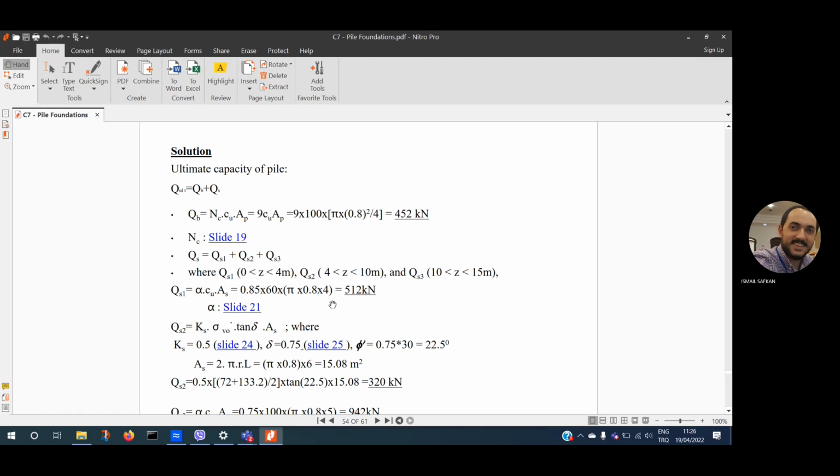That is my component for the second layer of pipe, calculated. But as I said, it's up to you as designer to neglect this component. You might not use it in your calculations if you don't trust the sand too much at that specific location. But if it's firm sand, I mean stiff sand, you might use it.